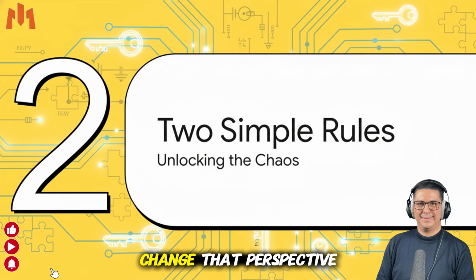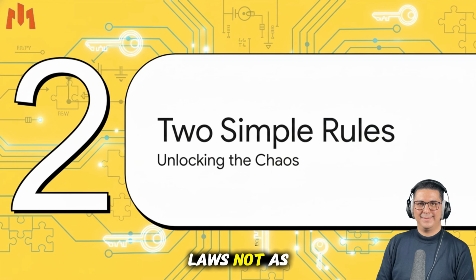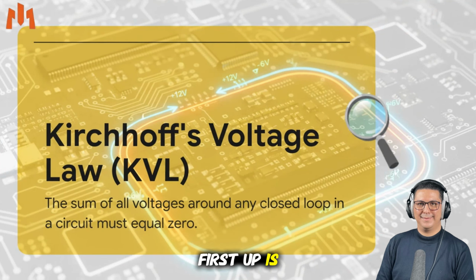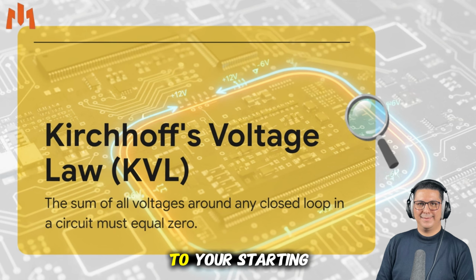So let's totally change that perspective right now. Let's reintroduce these laws, not as rules, but as the keys we need to unlock the hidden logic inside any circuit. First up is the voltage law, or KVL. Think of it this way. If you were to take a journey around any complete circle in a circuit, any energy you gain from a battery you must lose through components like resistors. By the time you get back to your starting point, it all has to balance out to zero. It's really just the law of conservation of energy applied to a loop.